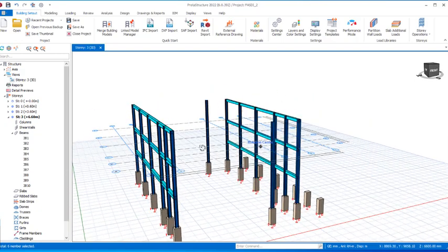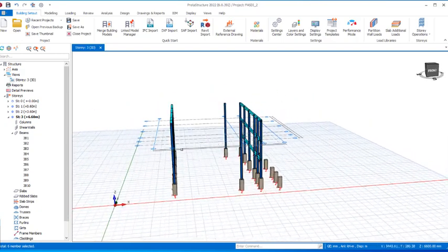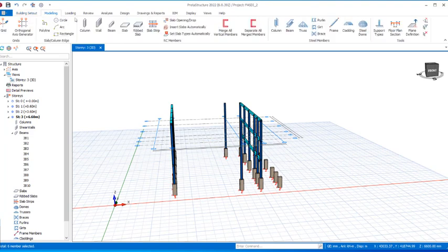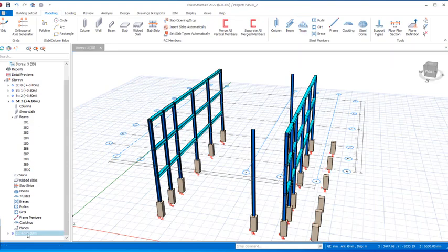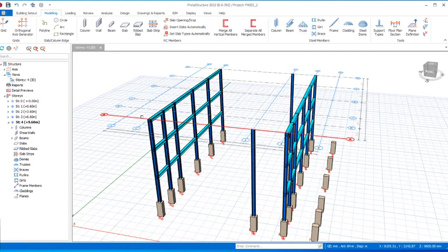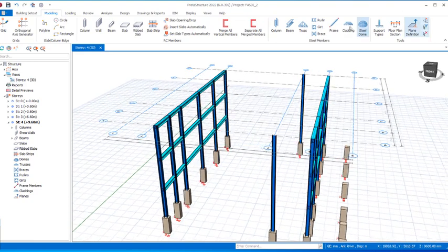We want to be placing the steel trusses successfully. So for the steel trusses, we have to navigate to the steel model, and then you come to truss right there. So we need to pick 2 points, and before then we are supposed to navigate to the top story, which is story 4. So we will double click on story 4 to move the grid lines to that story. Then click on the trusses again, pick this point as the first point, take it to this point as the second point, and then the trusses dialog will come up.